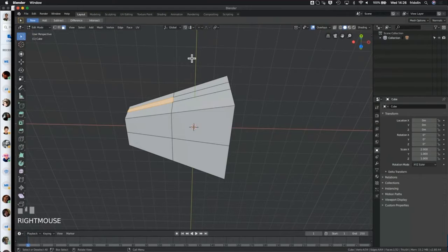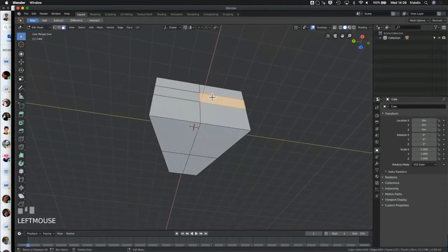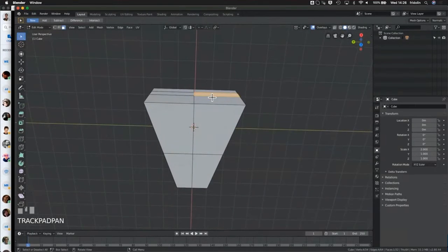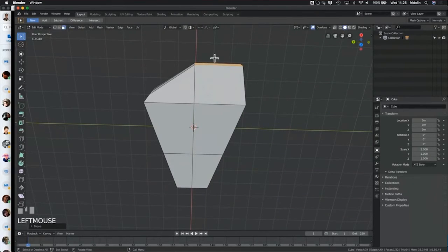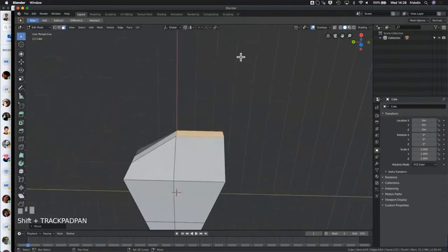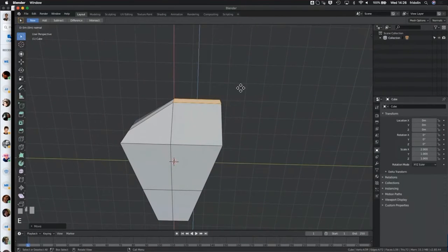The other really useful mesh editing thing, this is the last one that we'll look at, is extrusion. So extrusion is when you select a face and you don't just move it. Moving it is what we're doing here, where it pulls all of the other neighbors along with it. But if you extrude something, then it kind of copies the face, drags it out, but the neighbors remain in the exact same place.